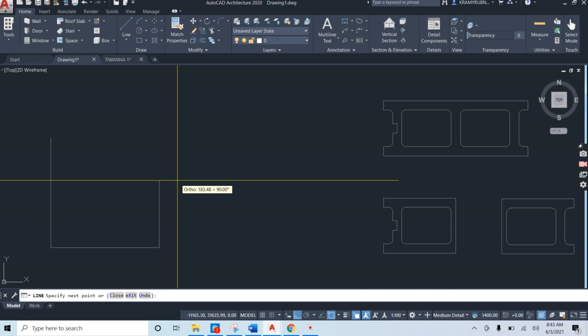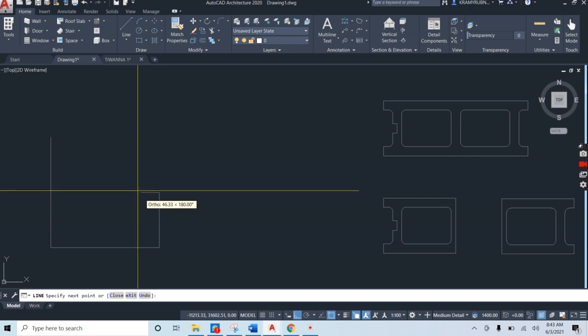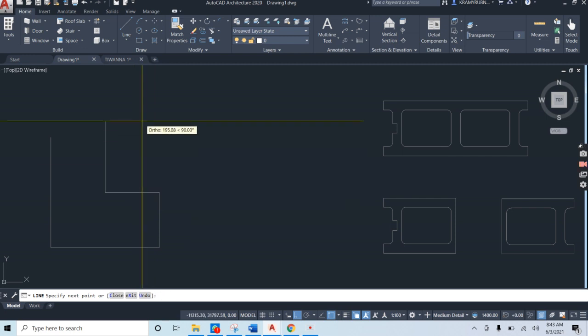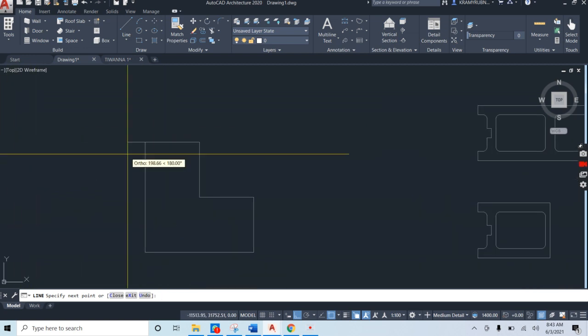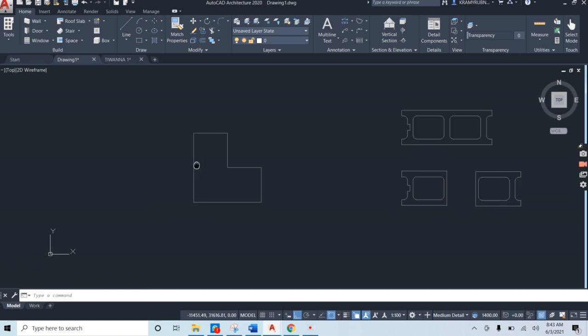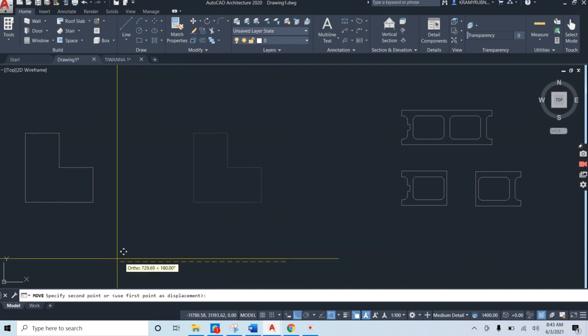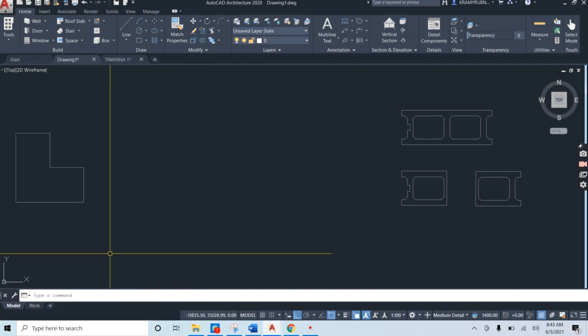But each branch is now going to be 150 millimeters. 150 millimeters in that direction. 150 upwards again until we have our closed traverse, 150 millimeters. We should be able to produce an L stiffener profile with relative ease.